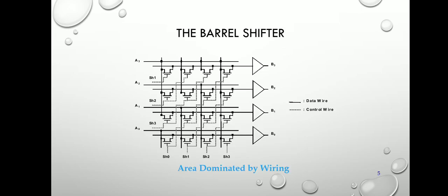In the case of the barrel shifter, it is a very important part of the combinational logic block, and it has the ability to shift data in a single operation, over standard shift left or right registers that utilize more than one clock cycle. It also rotates a number of bits in a cycle such that empty spots can be filled with the bits shifted off the other side.